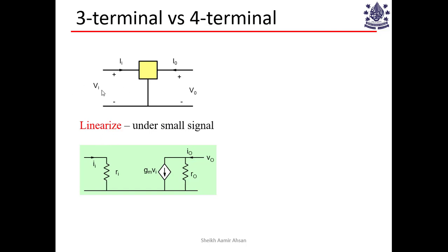So if a small voltage vi is added here, that is the small signal which is superimposed on top of this bias condition. And it is that small signal behavior that is being represented by this model: whatever is the additional current that will result on applying an additional vi, or an additional v naught. Just keep that in mind.